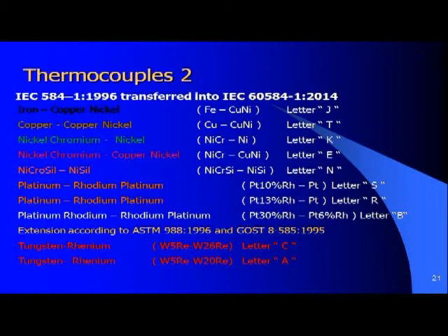So anyway, there are free positions in the crystalline structure which can easily be covered by strange elements, contamination, silicon, and of course also rhodium. So the stability of a type S is less than compared with a type R, because type R is an over-eutectic alloy. So there is always enough rhodium to cover all free positions in the crystalline structure.